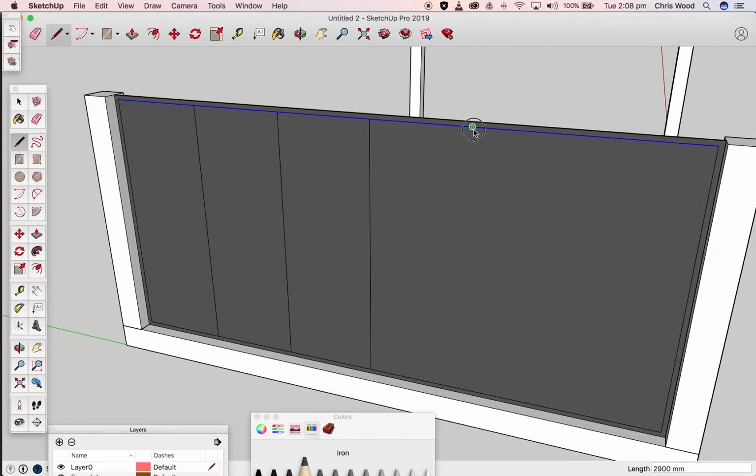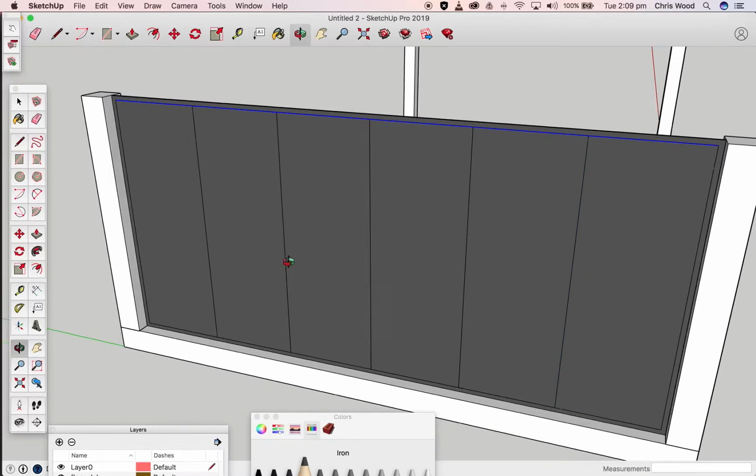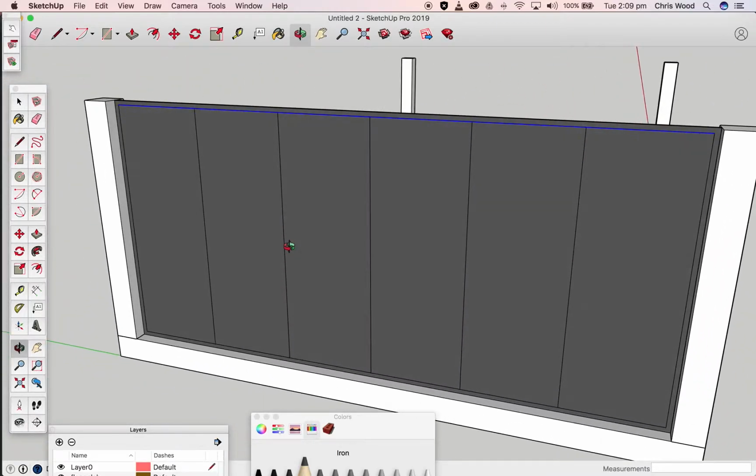And then, whoops, it lights up green. We come down, and there should be one more panel just around here somewhere. You've got to hunt around sometimes a little bit for it, and then I can just click down, and it's started to break that panel up into individual sashes.